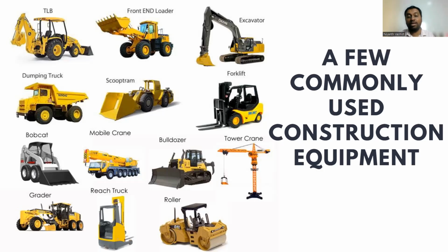The next thing will be a bulldozer, and that is something that we all know of. This is not to exactly excavate and dump it. This is just to transfer the entire surface of soil or any material which is on the land. That is why you'll be using the bulldozer. Next, we come into tower crane, where we are looking at skyscrapers. So wherever there are skyscrapers, that is where we look at tower cranes, where you need it to be fixed and the access point is very tall. Hence, you will be looking at tower crane, which will be 360-degree access as well.